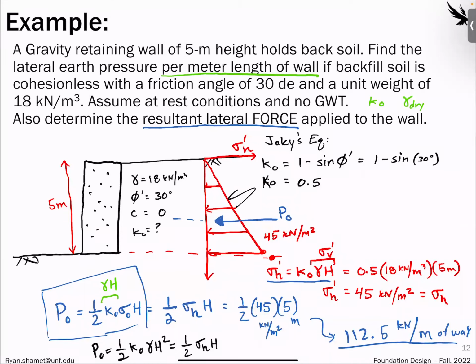Yeah, so the active earth pressure here, or sorry, the passive K naught. I don't remember who came up with it, but once you start looking into active or passive, it's the same thing, but you're just changing the K value. So you'd still draw the same profile, but this K value would be separate.